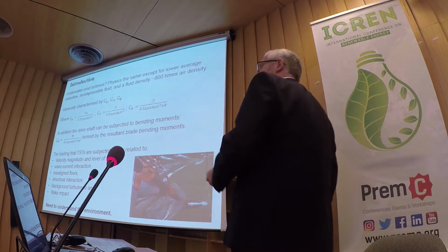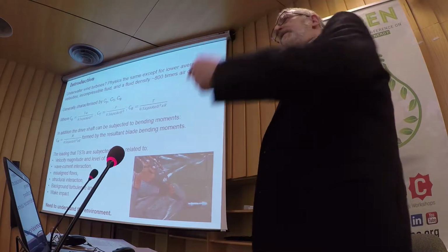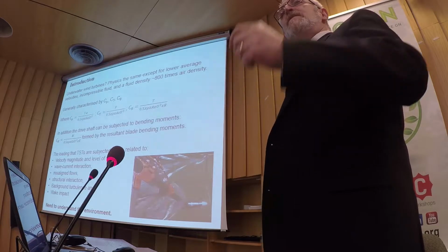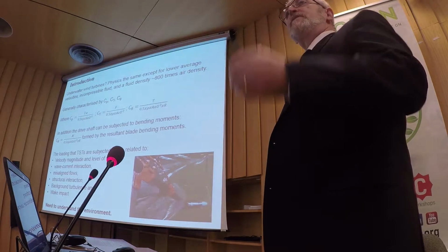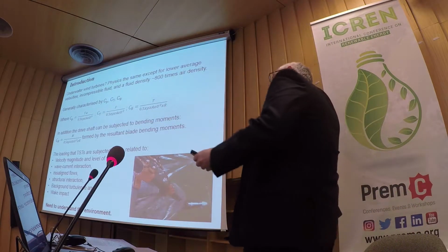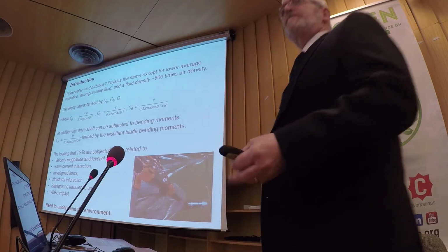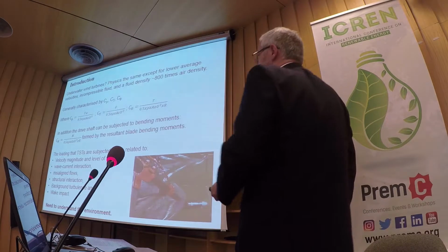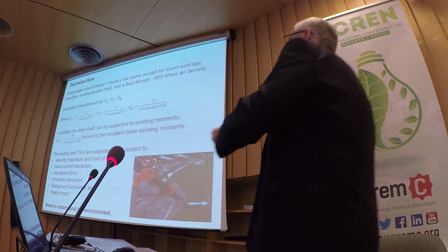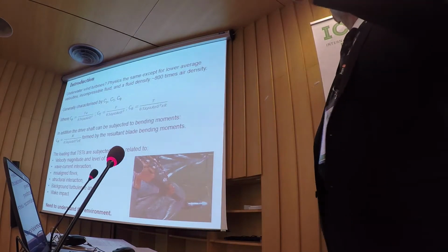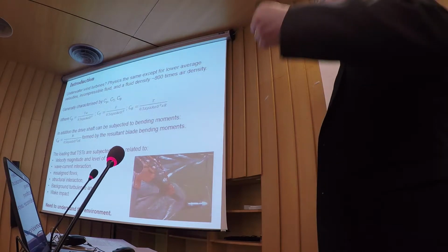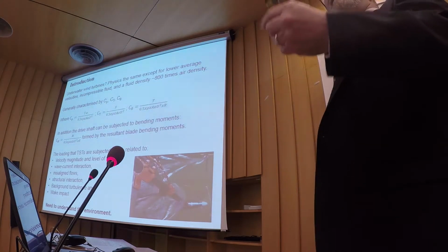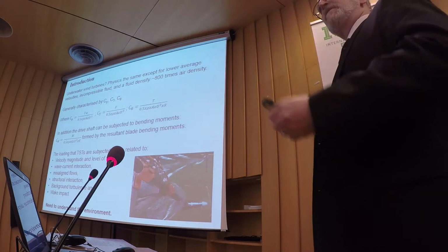Then there's the fact that water doesn't flow in one direction and out the other direction at 180 degrees. So there is a certain amount of misalignment. Should you yaw the turbine into that, or should you leave it go? Depends. Structural interaction. You've got to have a support structure generally. So as the blade passes in front or behind of that support structure, there is then a change in the characteristic for that blade.